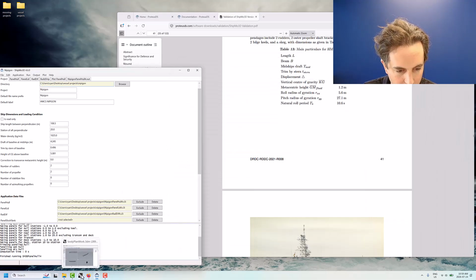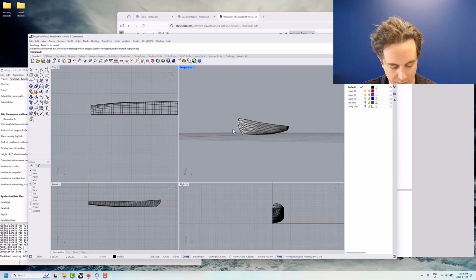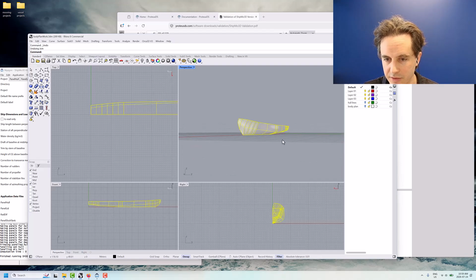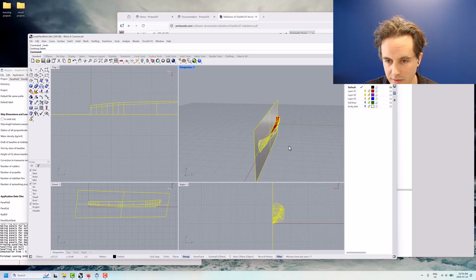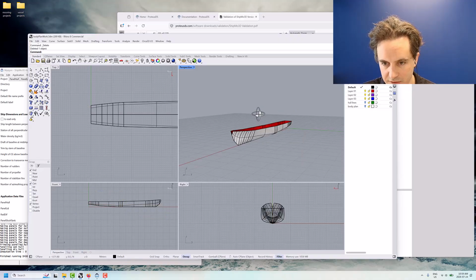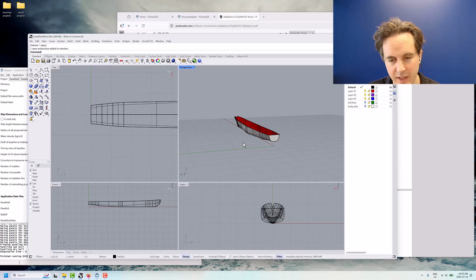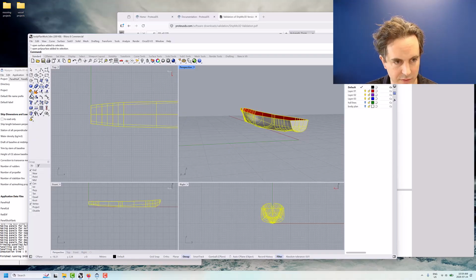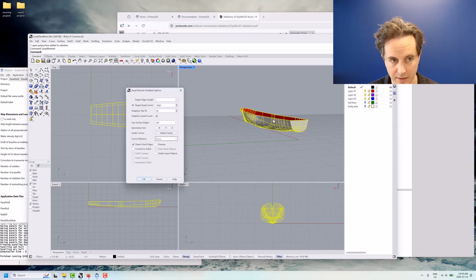If we go back to Rhino, so here's our mesh. So we just hit Control Z, undo, undo, and we'll actually work with the entire ship this way. First, you could do, it doesn't always happen. It's just one of those little sort of finicky things. So we have the surface, we'll join that up there, and we'll apply quad remesh to the whole thing.